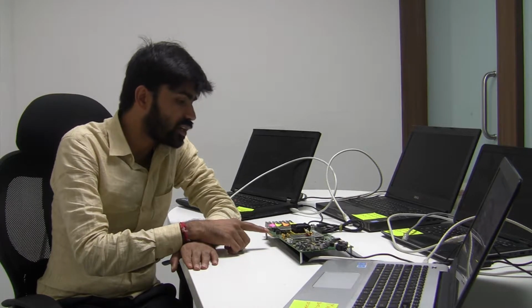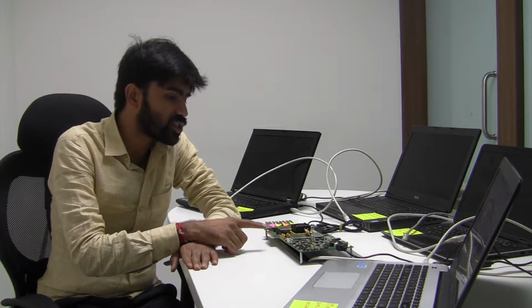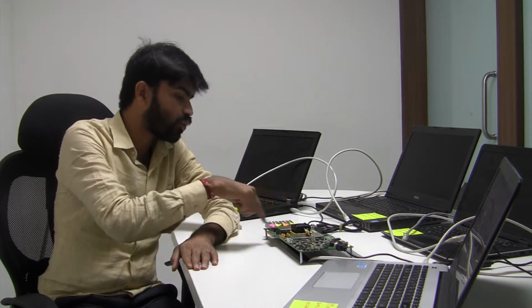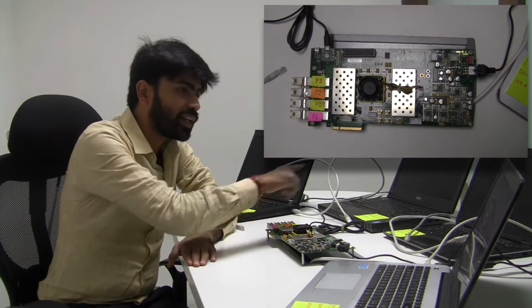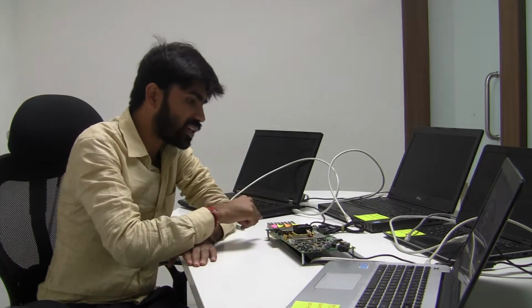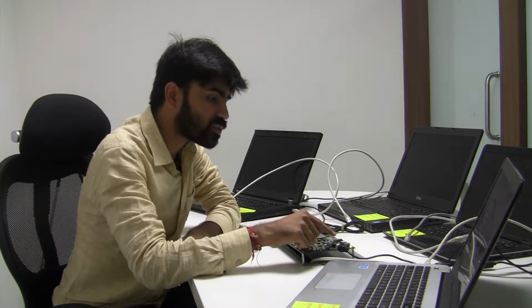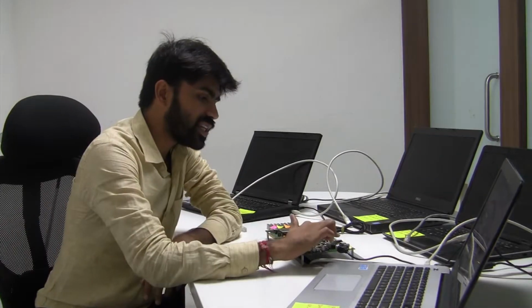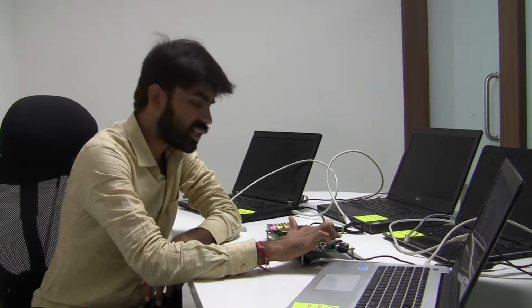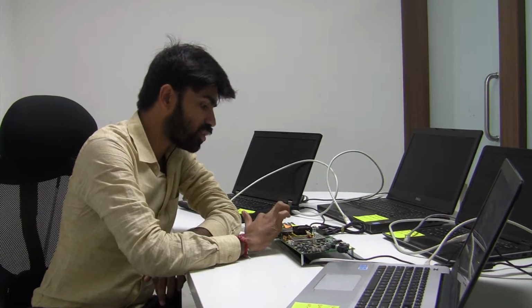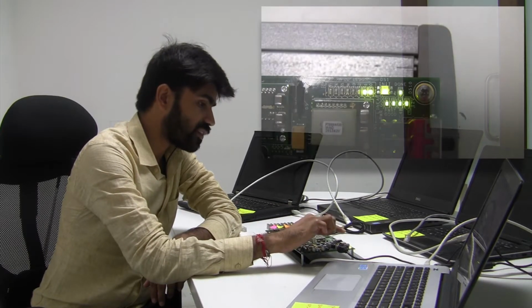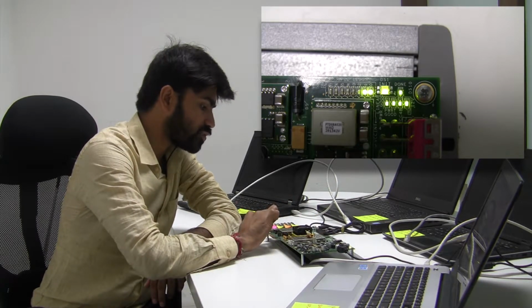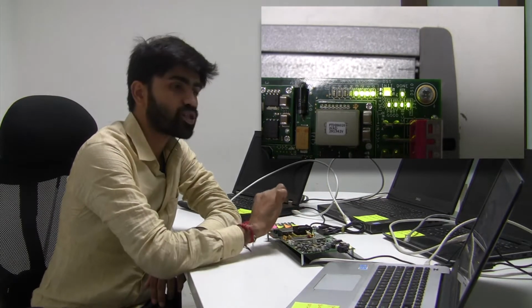So we're using the Xilinx Virtex 7 VC709 FPGA board, which has 4 ports. We can see that all 4 ports are not connected to any machines. In that case, let's check the link up status by checking the LEDs here. We can see that LED L4 indicates whether the link of port 0 is up or not. Similarly, LEDs L5, L6 and L7 indicate the link up status for ports 1, 2 and 3 respectively.